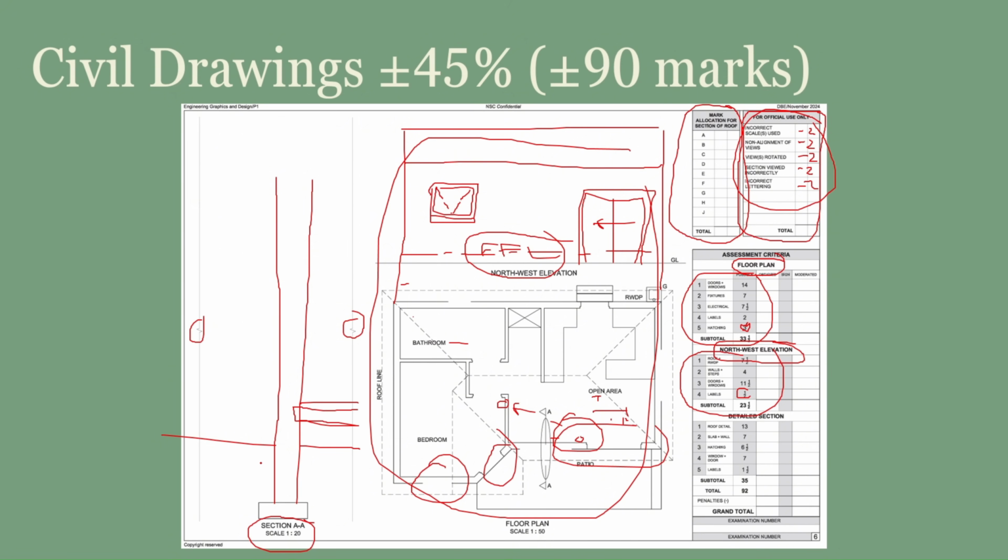So first things first, you're going to get your NGL, your natural ground line, the hardcore filling, which has a 45-degree hatching. Then it's the concrete surface bed with little dots and a few triangles. Then the undisturbed soil, you can put like a bubble around. It's 45-degree hatching in alternating directions. Then this is a screed. It's usually just little dots. And you need to add in the DPC here.